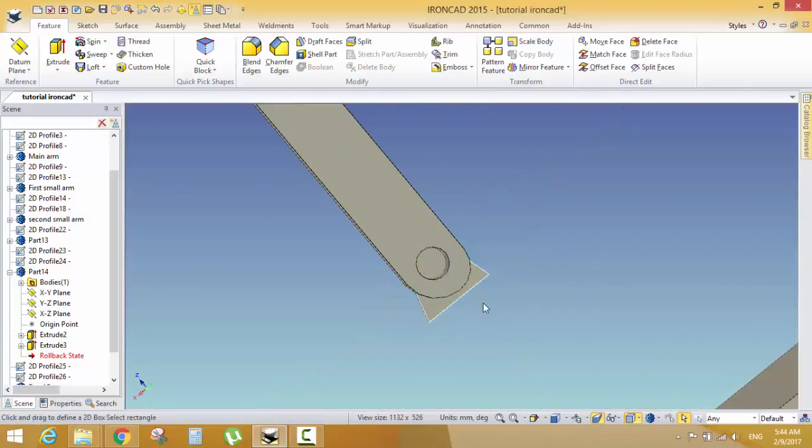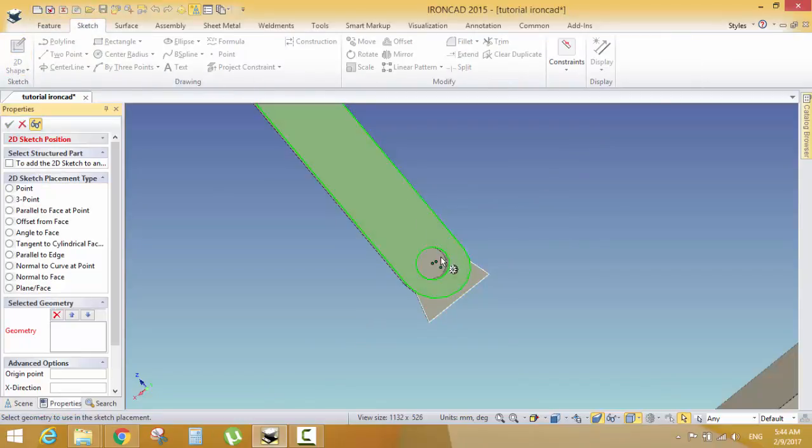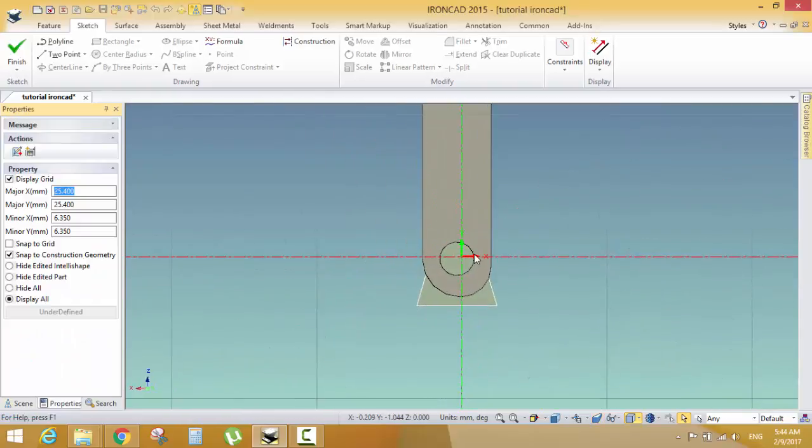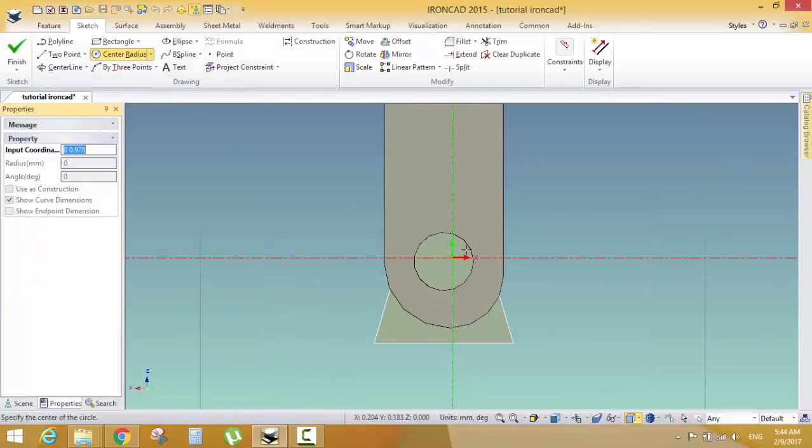Select the other face. Sketch 2D shape, the other face. Okay. Select the circle. Note that if you hover over the circumference of the circle, it will be highlighted. If you move around the circumference and get back to the center, your cursor will be snapped to the center of the circle.